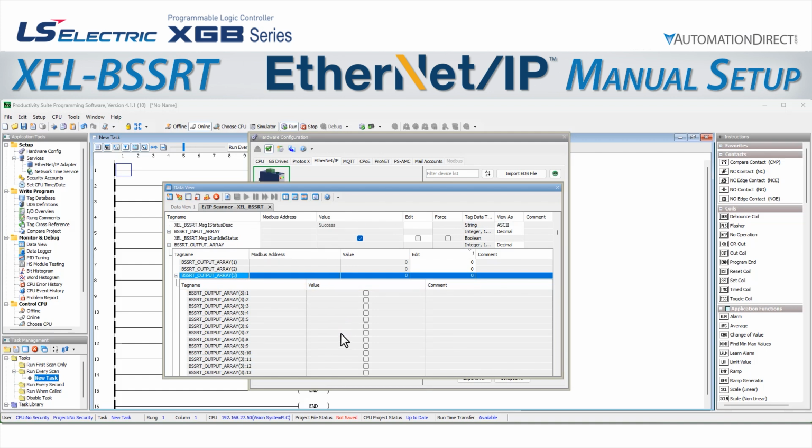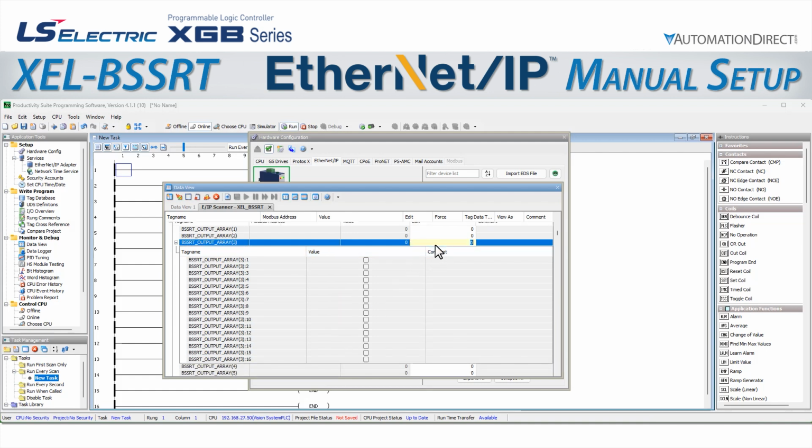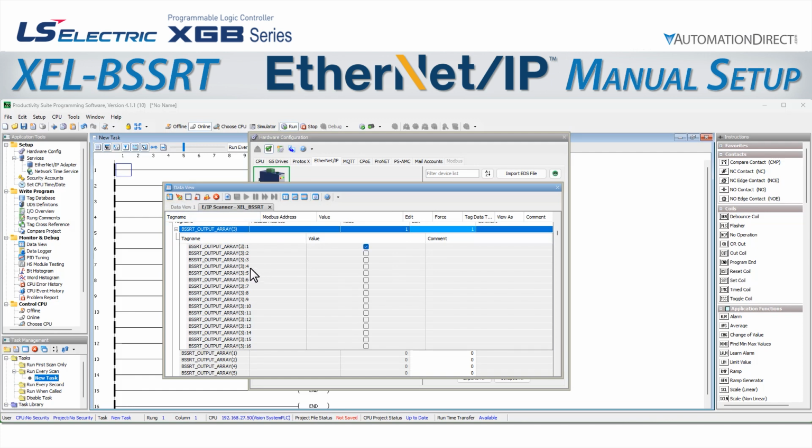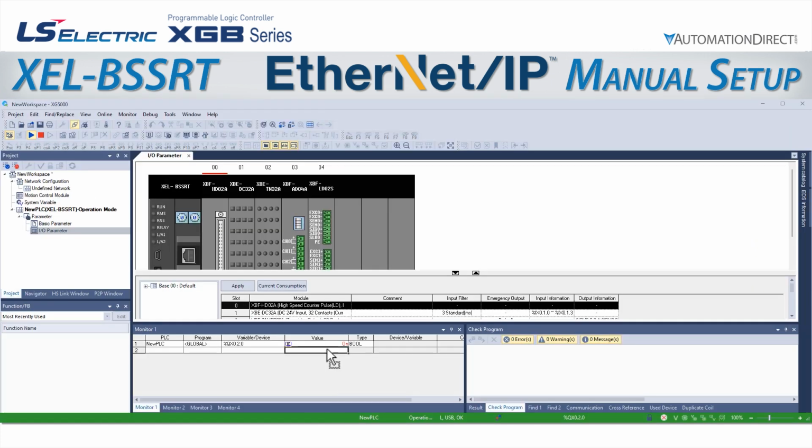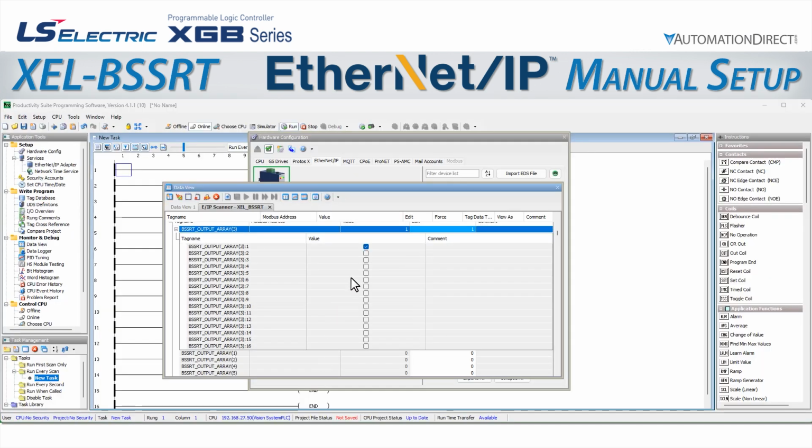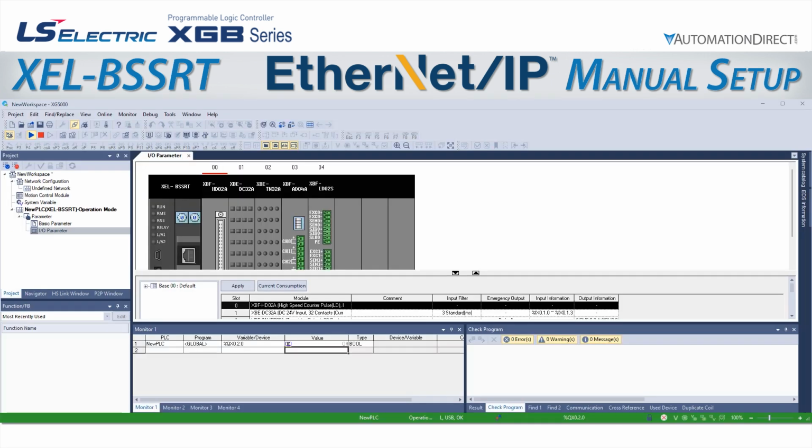We can write a value of 1 to the word, which will correspond to the first bit being on. We send the edit to the PLC, and if we look back at XG5000, we see that the output point has changed to on. Let's go back to Productivity Suite and turn that bit back off by writing a 0 to the word. And back to XG5000, and the point is back off.